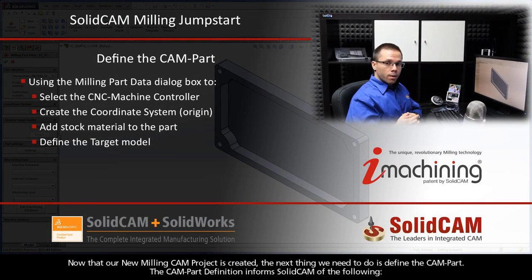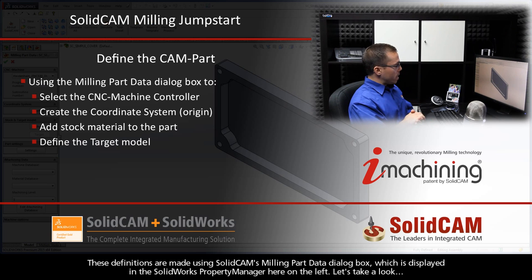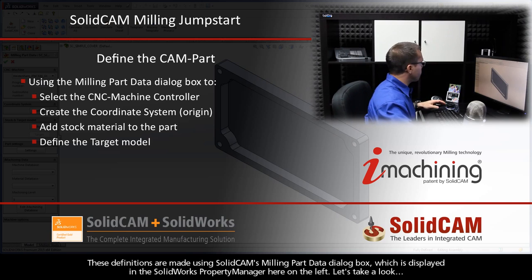Now that our new milling CAM project is created, the next thing we need to do is define the CAM part. The CAM part definition informs SolidCAM of the following: the post processor we'll be using to output G-code for our CNC machine, the coordinate system or origin for all our machining operations, and finally the stock and target models. These definitions are made using SolidCAM's Milling Part Data dialog box, which is displayed in the SolidWorks PropertyManager here on the left. Let's take a look.